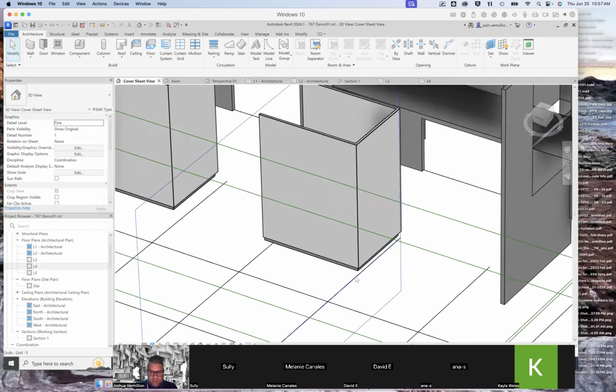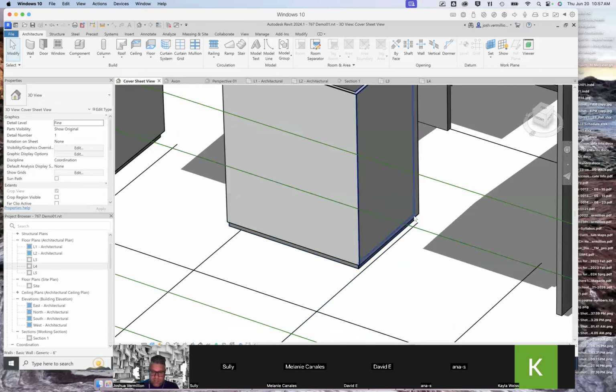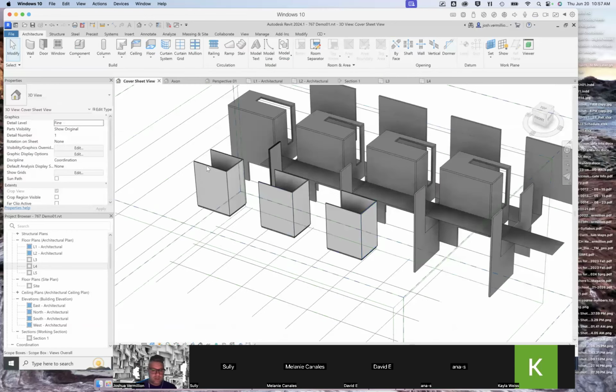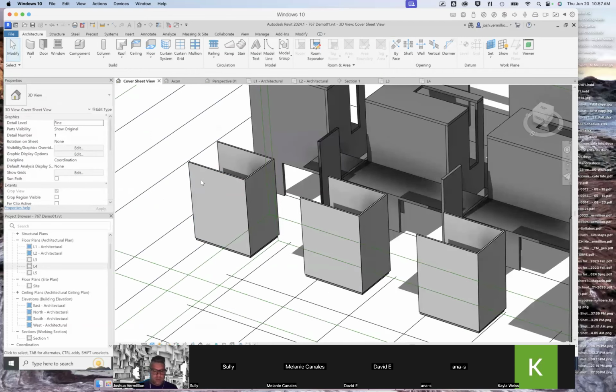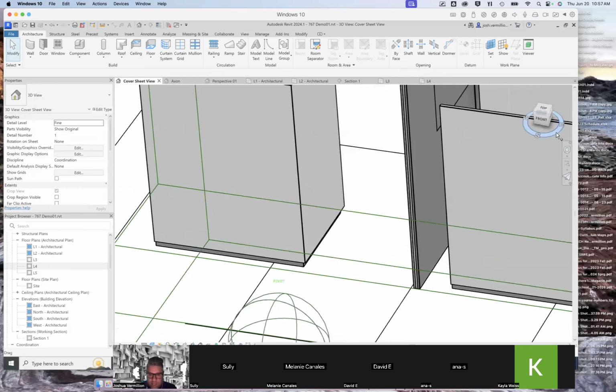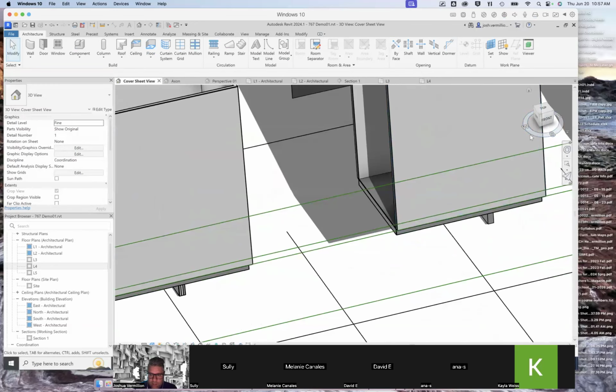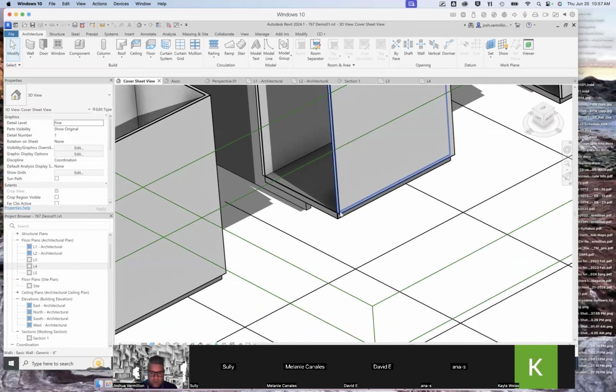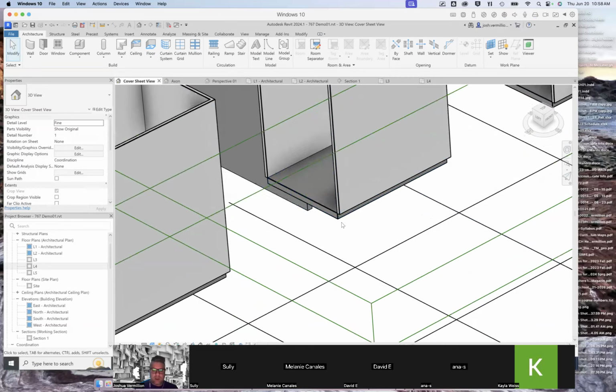Now, here's an interesting thing, right? Our walls start at level 3, and our floor starts at level 3 and goes down a foot, right? So here's another thing you can do. Just as we can offset floors, we can offset the bottoms and the tops of walls. If I move this around just a bit, you can see it a little more clearly. Our walls are just floating here, when in fact they would actually be anchored to the floor, to the slab here. And they might even extend down to become a fascia, and then there might be a soffit under here somehow, depending on what we're trying to do.